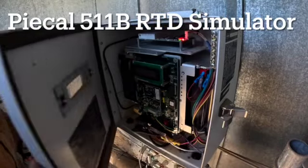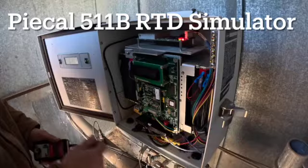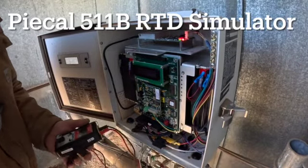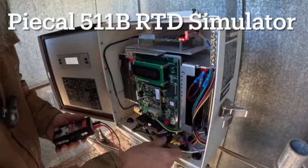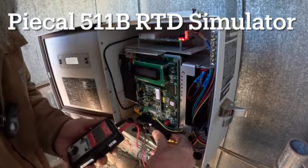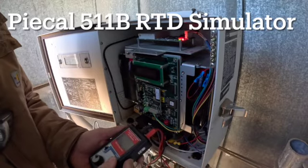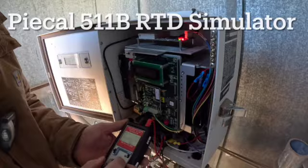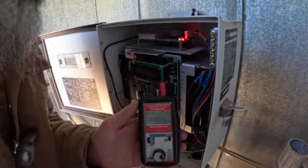Next, I will verify and calibrate the temperature by using an RTD simulator. To connect the RTD simulator to the meter, I will disconnect the temperature probe on the lower right-hand side of the main board and connect the RTD simulator. I will verify the temperature at 3 points, 0, 75, and 150.